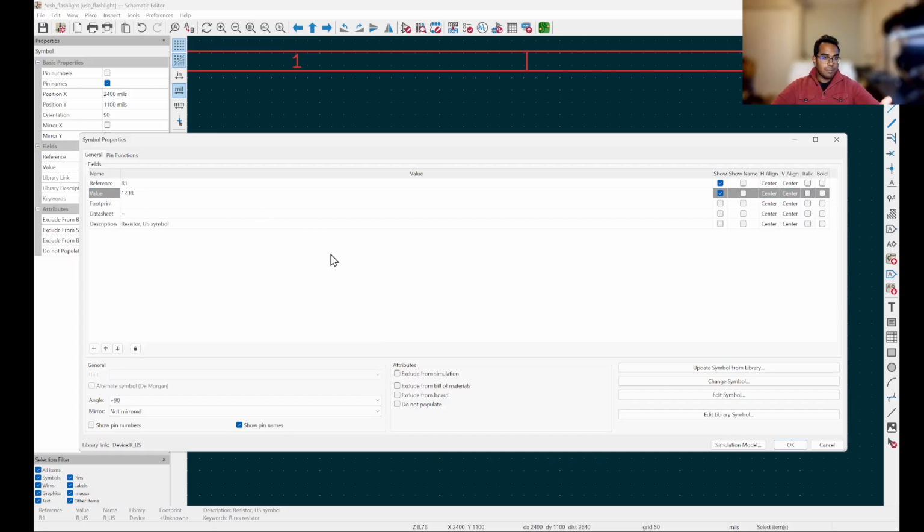I know that it's not the same notation as an ohm, but it's much easier to type a capital R than it is to type an omega on a keyboard. So basically most schematics that you read will use R for resistance. And if you provide this to just about any PCB manufacturer, they'll know that the R is referring to ohms on a resistor. So we have the correct value here.